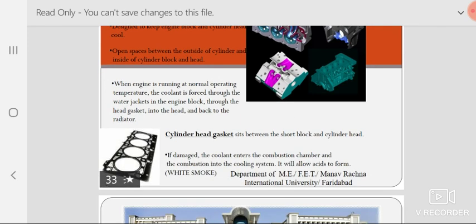Now gasket. There is the second term, this is gasket. What is a gasket? Gasket is generally used in case of pumps or any rotating structure in the casing to prevent leakage. See, in case of a pump, when you nut and bolt the outer casing and put a screw in that, even then the water is passing through that, and there is a chance to leak. Nut bolt tightening is not so foolproof. Liquid comes through it. So a rubber gasket is generally placed in between two nut bolted parts so that the liquid doesn't come out of that. That is to prevent the liquid from coming out.